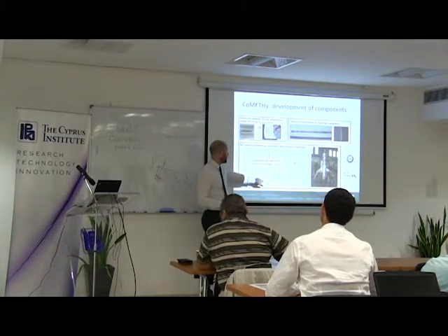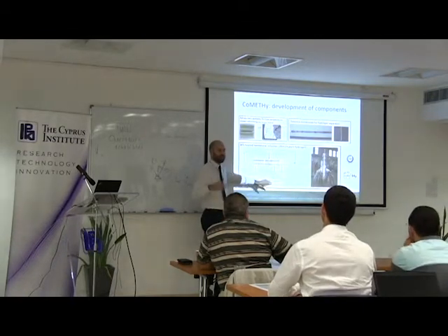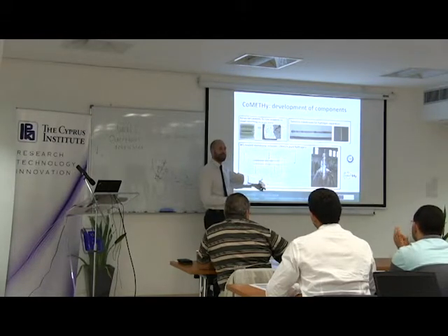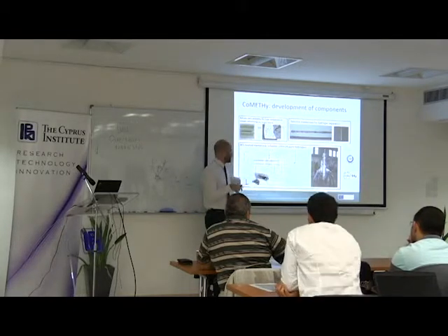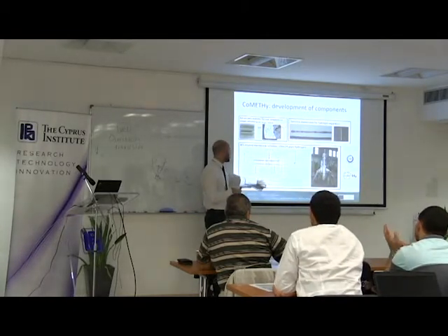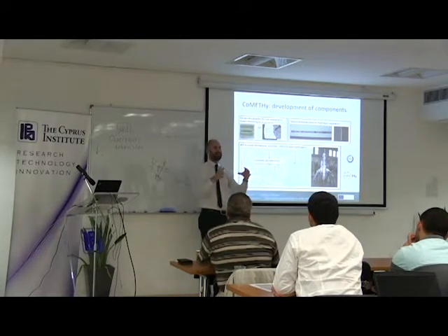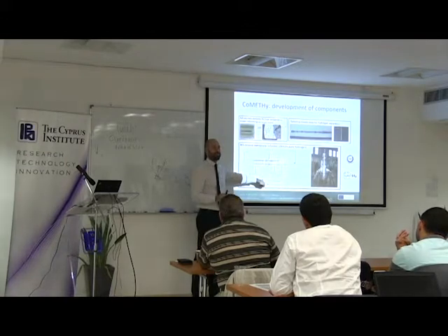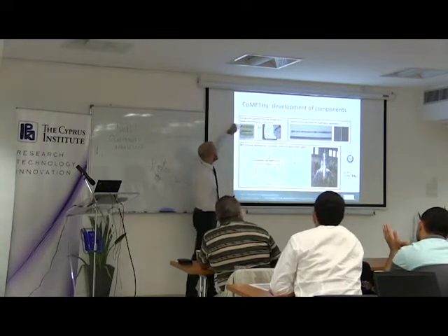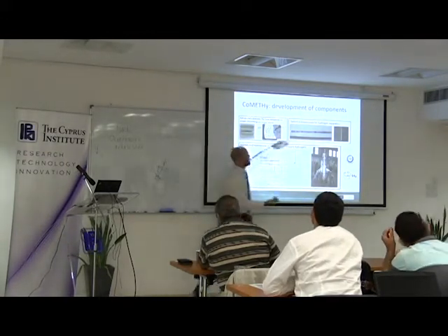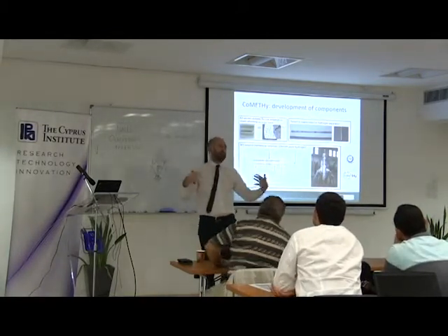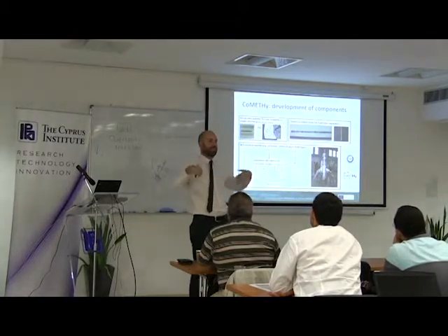Each tube, I think you're all familiar with the shell and tube heat exchanger. So the molten salt flows on the shell side, while the reaction occurs within the tubes. The tubes are actually a tube assembly, an outer tube and an inner tube, which is a hydrogen permeable membrane. You see it here. So the catalyst space, you see, is an annular space around this inner tube, which is the membrane. The membrane allows the passage only of hydrogen. All other components are retained and cannot cross the membrane.